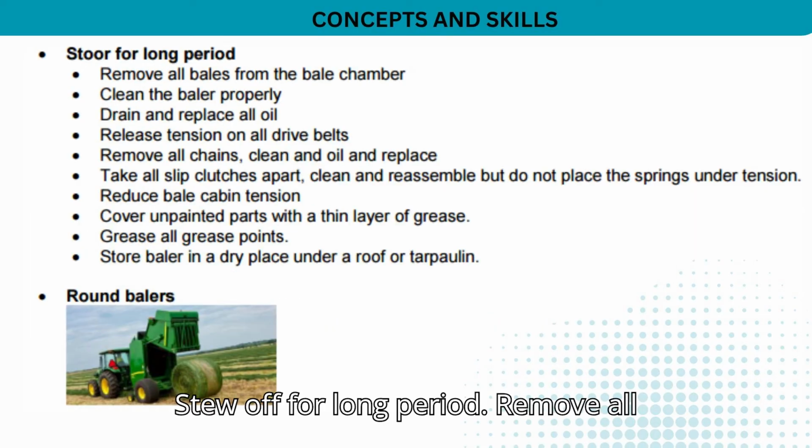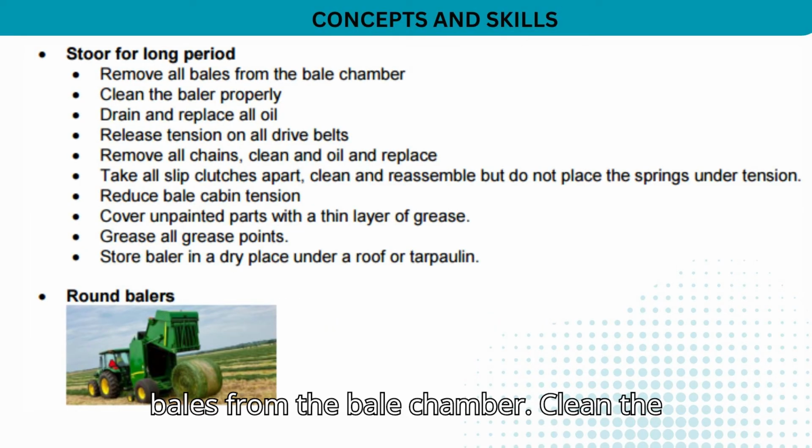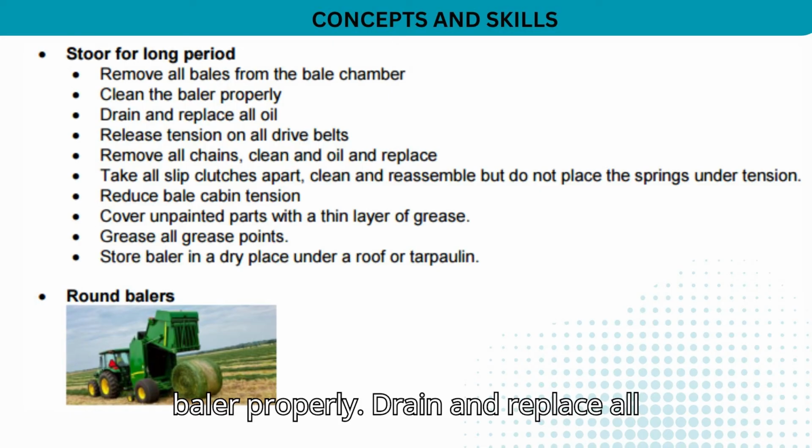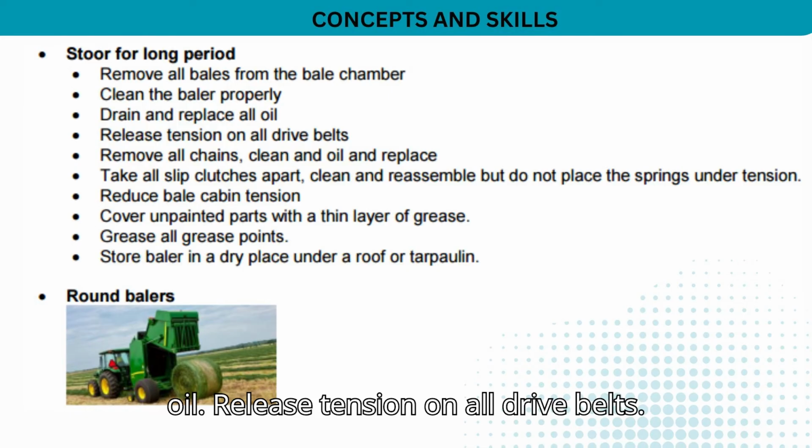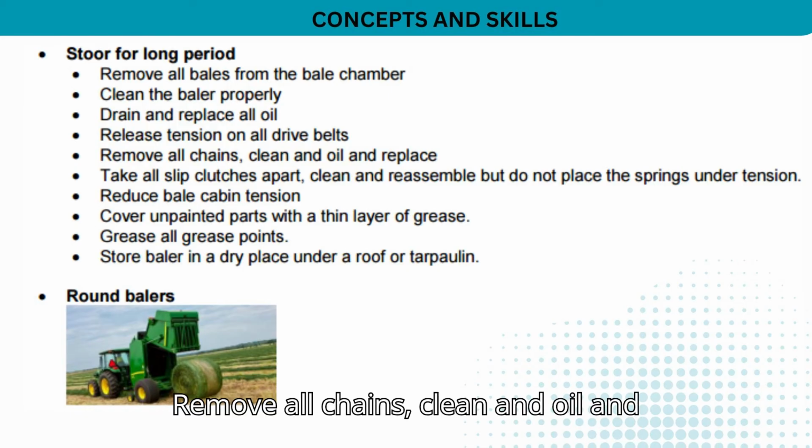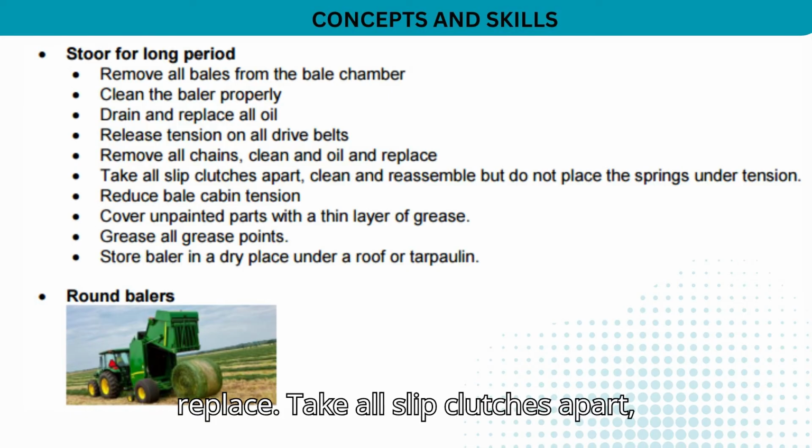Storing for a long period. Remove all bales from the bale chamber. Clean the baler properly. Drain and replace all oil. Release tension on all drive belts. Remove all chains, clean and oil them and replace.